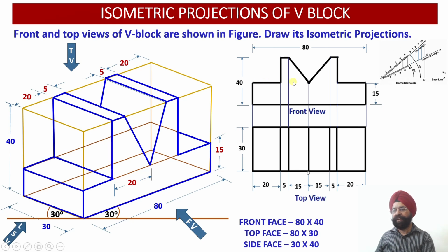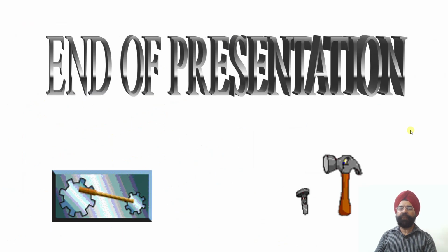So we started with our first element, which was a block having a shorter thickness. Similarly, then we picked up this element, then we picked up this element, then we picked up these two elements. This way you need to break up the information of the complete solid into elements, and only then will you be able to complete the construction of the isometric projection from the information of the orthographic views which are available, right? So this is all for today.